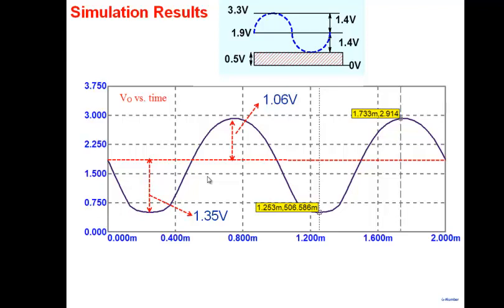Yeah, so if the gain of the amplifier is not that much, the small signal sinusoid that you have applied at the gate would not actually be very small. If it is not small, then your gate voltage is fluctuating, so your VDS is fluctuating. So that 0.5 region is actually not 0.5.